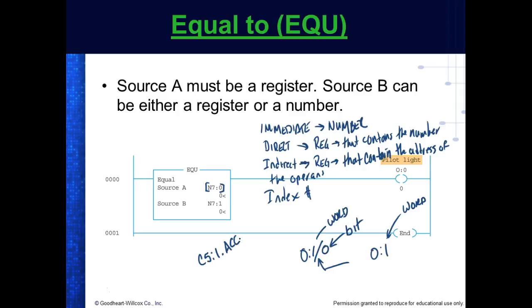Well, that applies to counters and timers. But when we're doing outputs and inputs, well, just outputs, that's what we're writing. Yeah, because we don't have to specify which 16-bit register, because this is the address of the 16-bit register. But when I get into a counter, how many 16-bit registers does the counter have? At least it's got to have an accumulator register, right? You understand that? Now the done is a bit within a 16-bit register, right? Counter done, count up, those are bits.